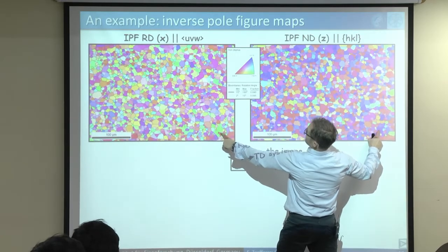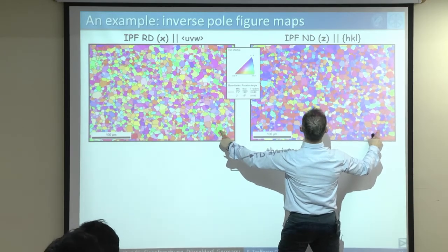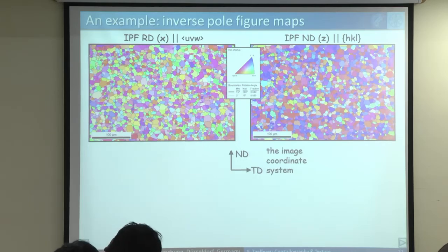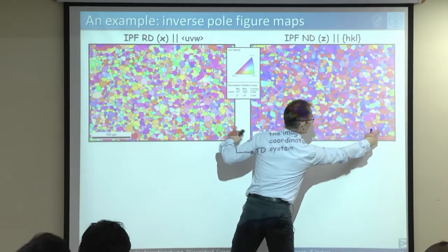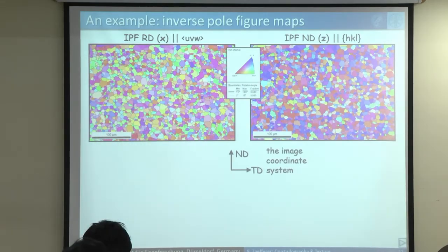So it's the same grain. It is 110 in UVW, and 111 in HKL. So this seems to be UVW 110 or 011, and this one, oh, by chance this is exactly the orientation I wrote down here as last. So this grain here, indeed, has the orientation 111, 110. And let me show you this shortly.